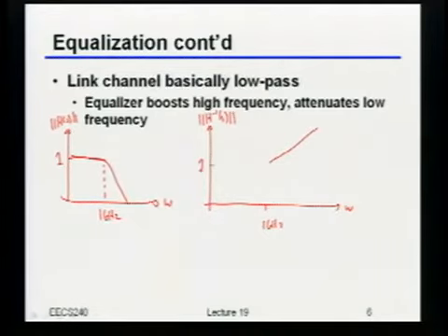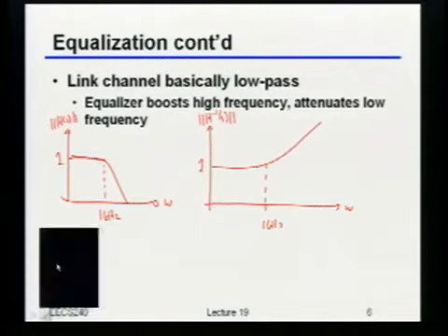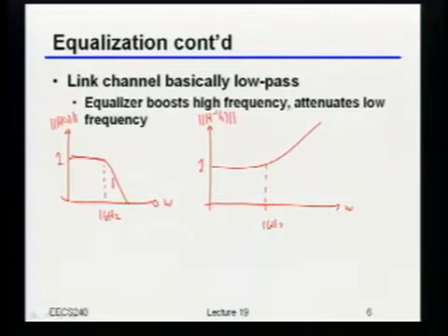So I should have something that basically, and let me draw that a little bit more cleanly, does that, right? Now, by the way, I never explicitly said what type of channel this was, meaning if this is a first order roll-off or second order, but let's, as an example, assume it's a first order channel. So let's say that's a single pole at a gigahertz, then indeed, if I build the inverse, it should just be a high-pass filter with a 0 at 1 gigahertz.